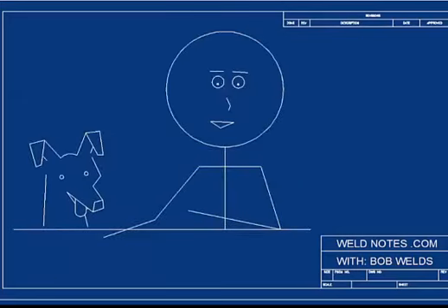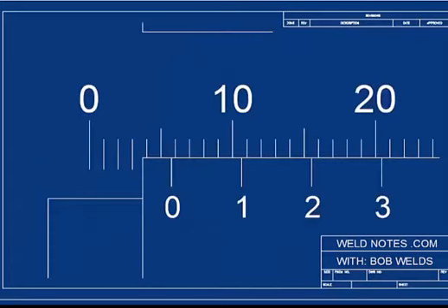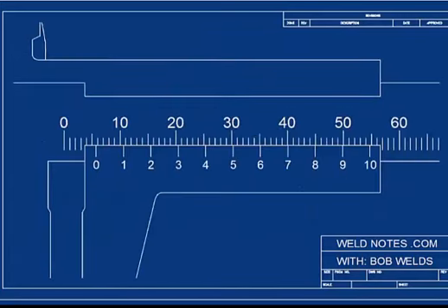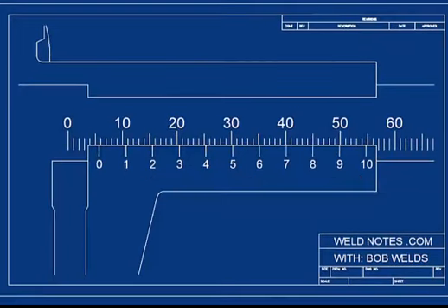Okay, you're ready to see the vernier scale, but I'm only going to draw the main part of it first. Now, you see the marks number from 0 to 10. Each of these marks represents a tenth of a millimeter. They're going to tell us the tenths of a millimeter, and here's how they work. Look carefully, and you will notice that one of the marks on the vernier scale lines up better with the main scale marks than the others. Which one looks like it lines up best to you?